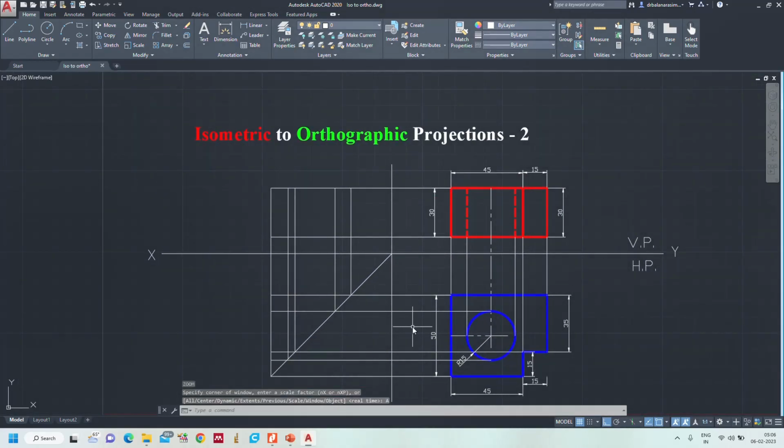Yes. So the 45 degrees line, and then draw the horizontal projectors. From here you draw the vertical projector, vertical lines. If you observe, this is the one which matches this one. So this is the rectangle from here to here, the complete one, from this line.